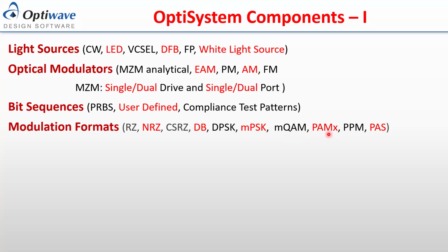PAM, we can generate any type of PAM, PAM4, PAM8, even non-standard types like PAM3, PAM5, PAM7. Pulse position modulation, as well as probabilistic amplitude shaping, where you can control the probability of each symbol in your transmitted PAM or QAM signals.